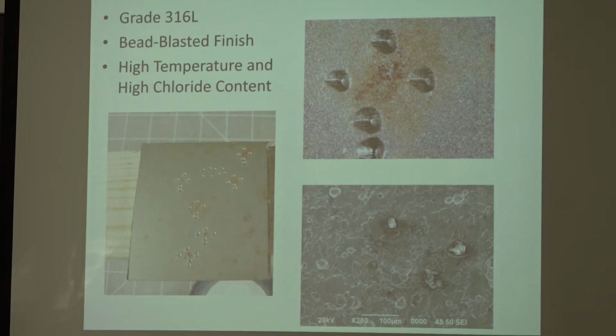It's stainless. I can do whatever I want with it. No, you can't. And the problem is, as soon as you start pitting that stainless steel, it's very hard to get it back because now you created holes. And so you can brush off the rust, but you'll have a problem again. So we went on and did a lot of ways to try to solve their problem in this particular case. And at the end of the day, they had to blast it. They had to, and it was most of it.